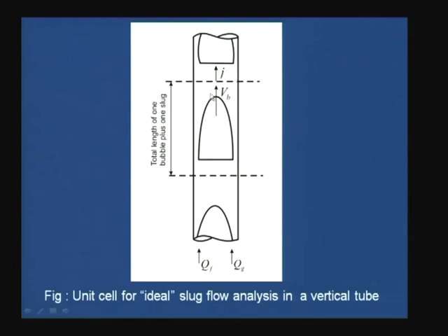Okay. So, therefore, we find that this rises up at a velocity ub, which is equal to ug, the in situ gas velocity. Now, at the bottom of the passage, air and water, or rather gas and liquid, are introduced at flow rates QL and QG. Okay. And these two phases keep on flowing up through the flow passage.